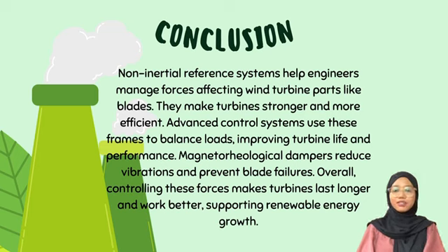In short, non-inertial reference systems help engineers manage forces like centrifugal and Coriolis forces that impact rotating parts like blades and nacelles in wind turbines. These systems allow for stronger and more efficient turbine designs by considering how these forces affect performance. Advanced control systems like individual pitch control use non-inertial frames to balance uneven loads, boosting turbine lifespan and performance. Magnetorheological dampers reduce vibrations and extend component lifespans by addressing blade failures from material fatigue and environmental stress. Overall, understanding and controlling forces in rotating systems enhance turbine durability, reliability, and efficiency, supporting the growth of renewable energy.